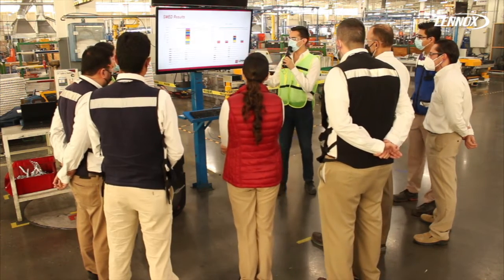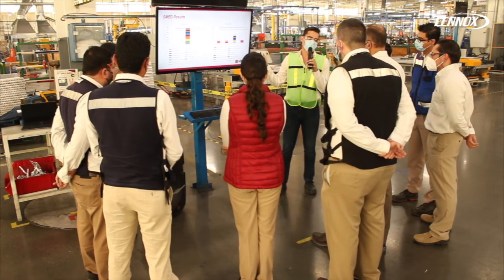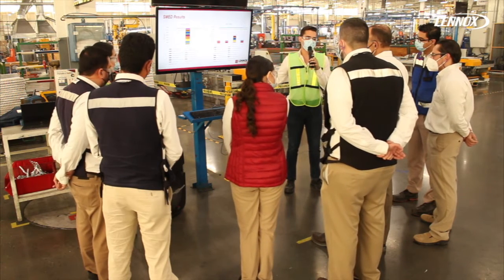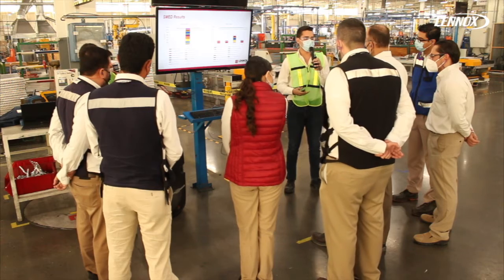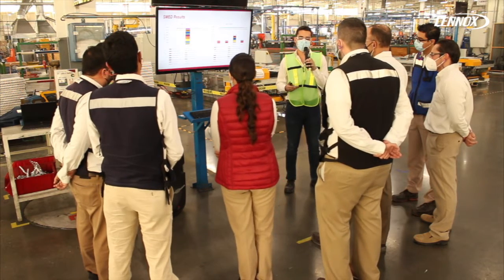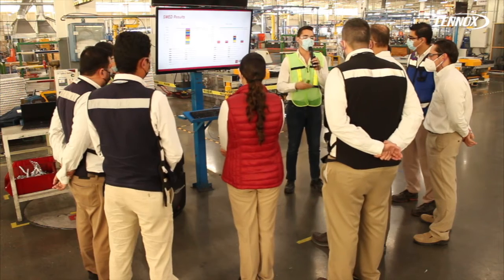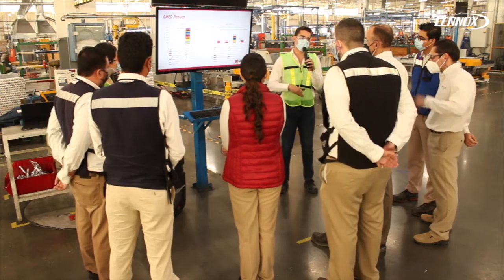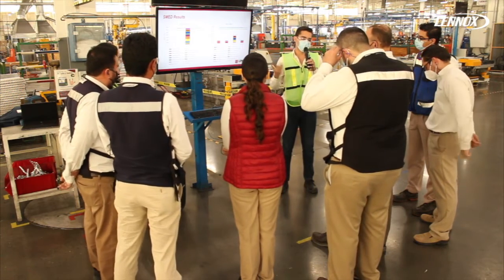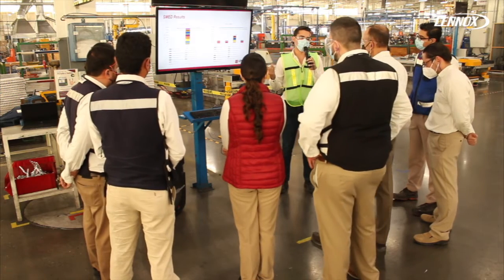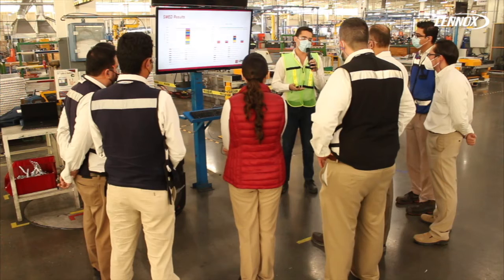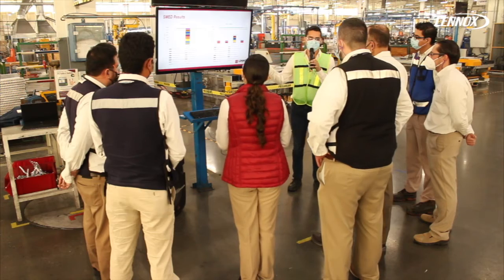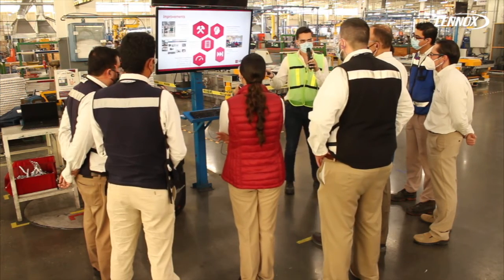And as we can see now in the right part of the screen, after the SMED methodology implementation, the technician is still working in the setup change, but in addition to the technician, we have both expander operators in order to change from sequential activities to simultaneous activities. We also have the external activities taken out of the pacemaker, in this case the technician, because right now the activities are done with the machine still working, so they don't count in the time that the machine is stopped. And well, to see how we achieved this change, we are going to see the improvements that we did during this project.